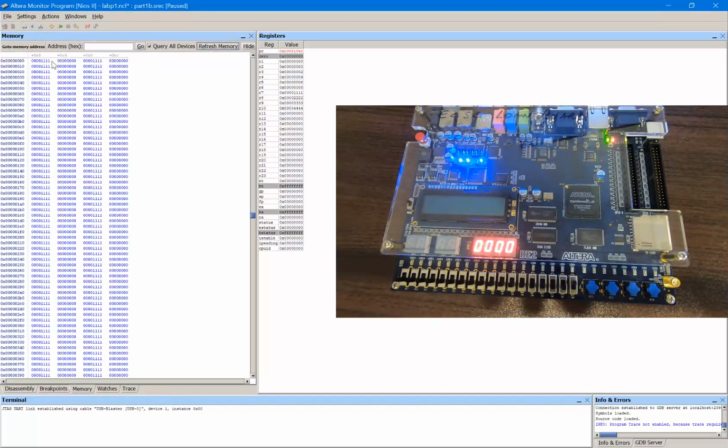So it wrote to this address here, the half word starting at 0. So it wrote those 4 ones. Now I told you that it repeats every 8 addresses, which is every 4 half words. So 1, 2, 3, and then 4. So at address 8 here, it's repeated again, and then it's repeated again there and there. Okay, because they're all referring to the same slave register. But now instead of all of this referring to that slave register 0, it is now all of this column, these 2 columns.